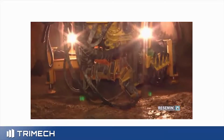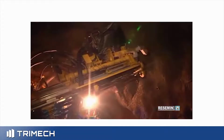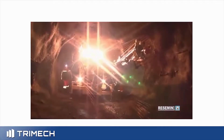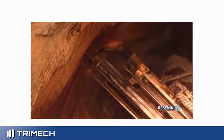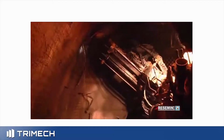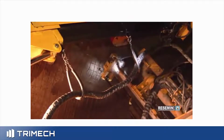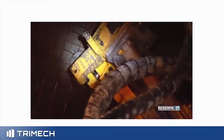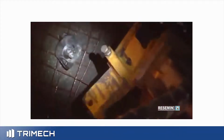So what we're seeing here is the vehicle has to be nimble enough to get into the mine, maneuver around, and then these big articulated arms are going to pick up a piece of wire mesh, hold it up to the wall of the mine, and then a second arm is going to both drill a big hole in the wall of the mine and then insert a giant threaded bolt into the wall to hold up that mesh. Now that mesh on its own can protect from falling rock, or sometimes if they really want to improve the stability of the mine, they can spray it with concrete to hold everything up. You see the bolt being placed in here, held with a claw, and then let go as it's finally finished.